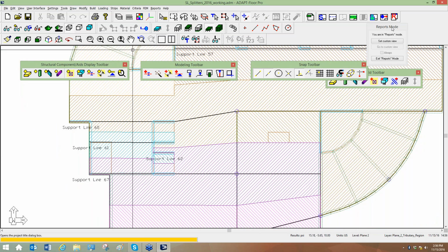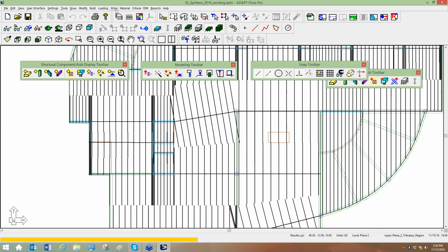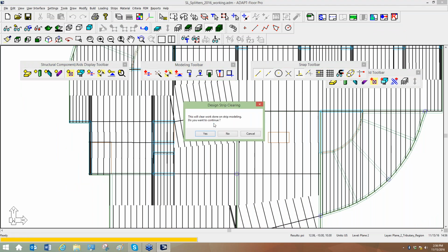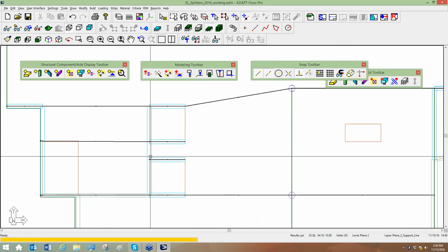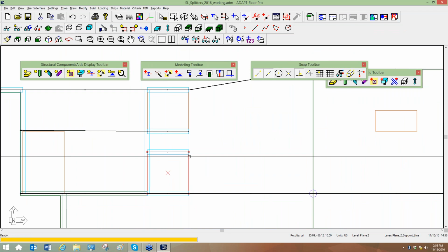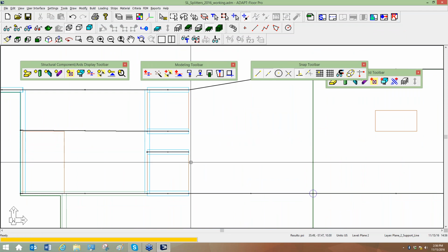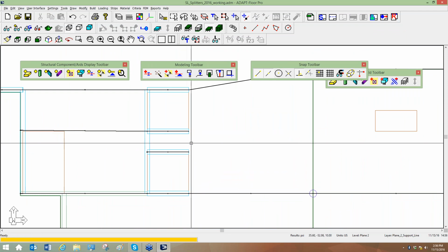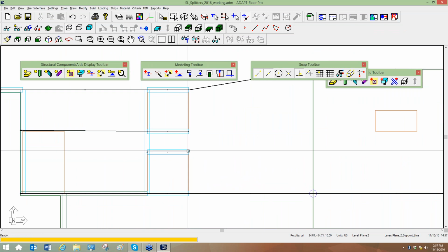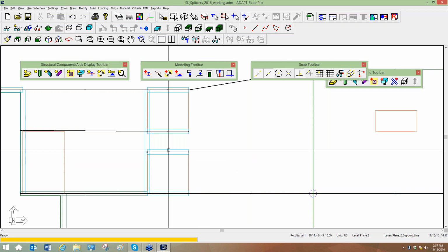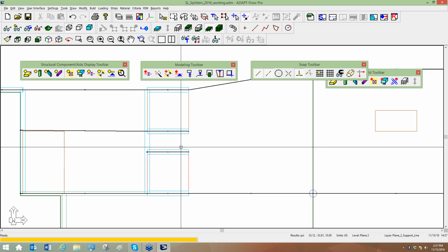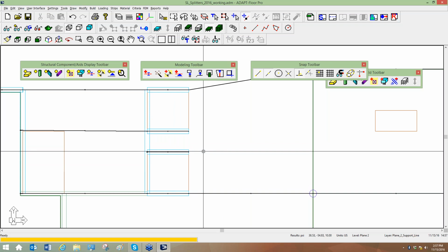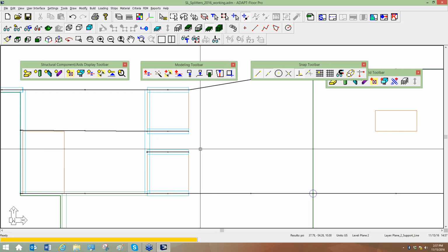Yes, the question really is, these walls right here, if I was to take a design cut at some distance away from the edge of that wall, you're going to have negative bending, and it's going to essentially dissipate and have some point where it goes to positive in this bay. So the question is, should we extend this support line out a little bit to pick up the effects of that negative bending? I would say yes.